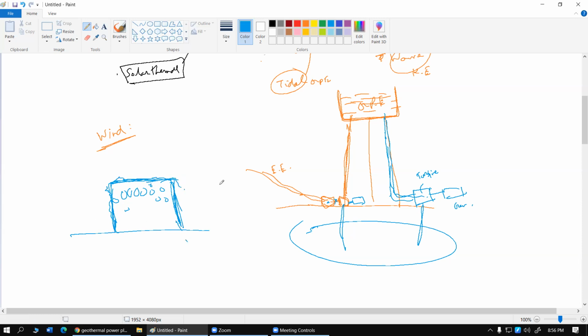So inside this, we're going to have some electrical heating coil. In the day period, we're going to provide electrical energy to this coil. This will heat up these stones. The stones are going to work as our heat energy source. And in the night period, we're going to have some pipes over here. Let me draw those pipes a bit thicker. Let's say we're going to have some pipes over here. These wires and pipes are not connected. Through these pipes, we can flow in cold water, and hot steam can be taken out. So in that case, these stones are going to give up heat and boil the water.